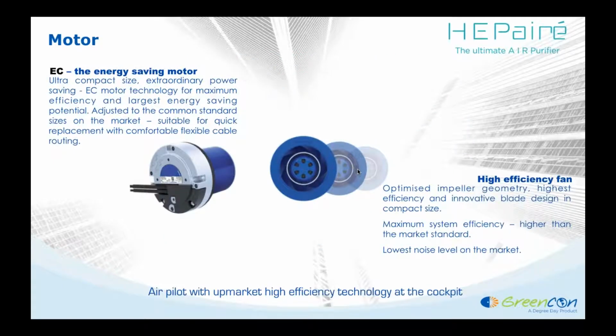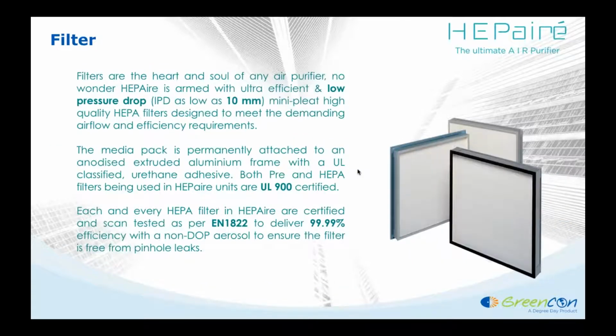EC motors are the rule of the game, as we all are aware. They help both in reducing energy consumption at lower speed as well as having a very low sound in the overall process. Filters are the heart and soul of it. Filters are available in various media, in various depths, at various static pressures. It depends how you size it. In our case, our initial pressure drop is as low as 10 mm. So we have taken a very huge capacity HEPA filter and sized it for a very low capacity airflow to ensure that it goes on and on for a very long time without needing a replacement.